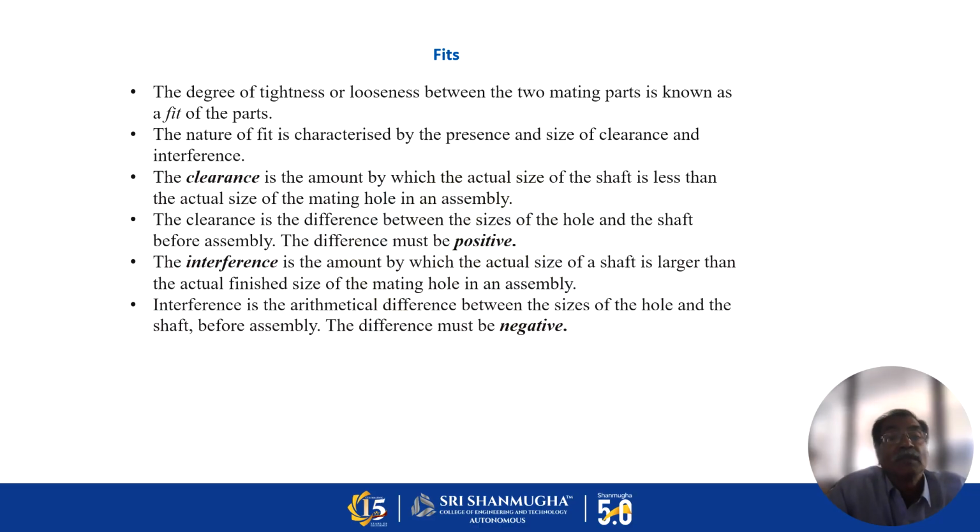Fits. The degree of tightness or looseness between the two mating parts is known as the fit of the parts. The nature of a fit is characterized by the presence and the size of clearance and interference. Clearance is the amount by which the actual size of the shaft is less than the actual size of the mating hole in the assembly.